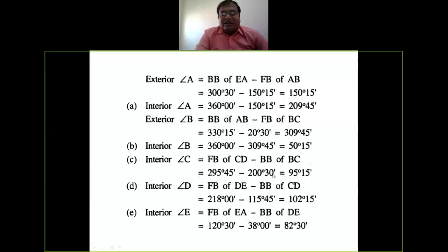Same way you can calculate angle D. Angle D के लिए क्या चाहिए? Forward bearing of D in forward direction and back bearing of CD. Here forward bearing D is greater than back bearing CD. You just take the difference and you will get your answer. Now here you can see again angle is inside the traverse.